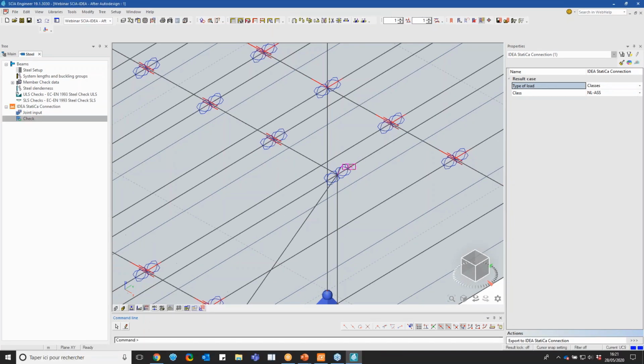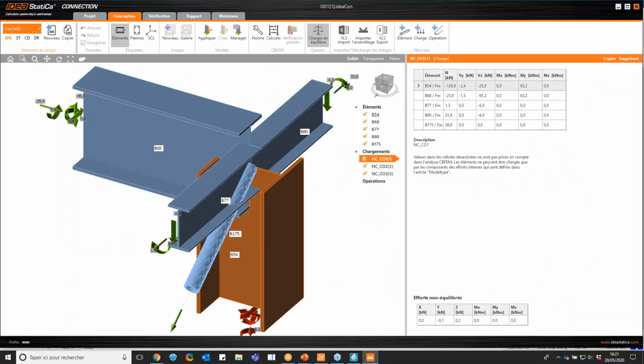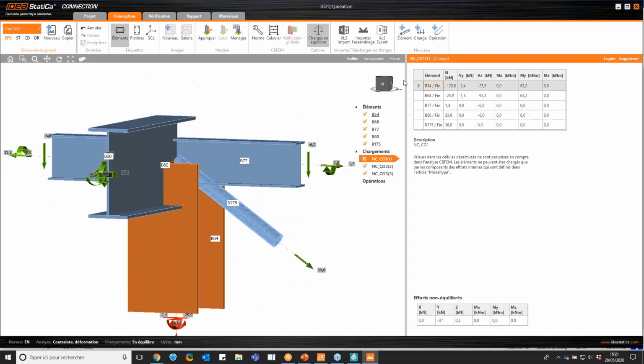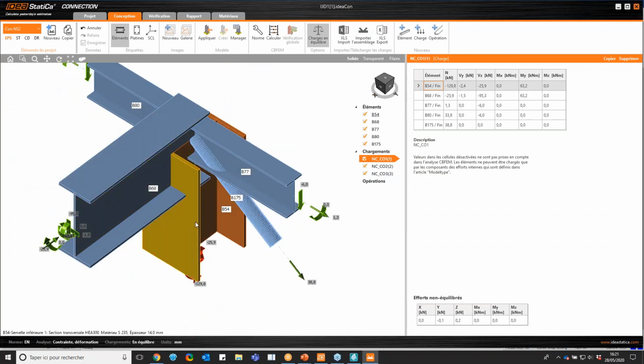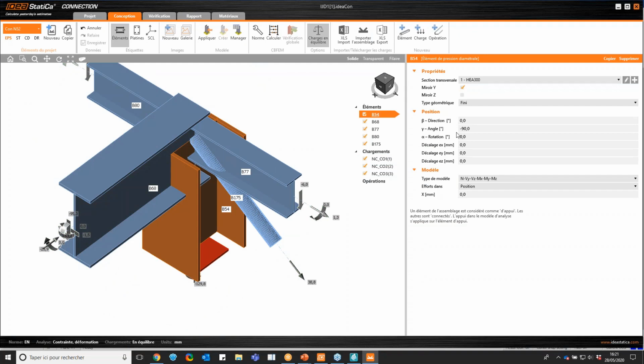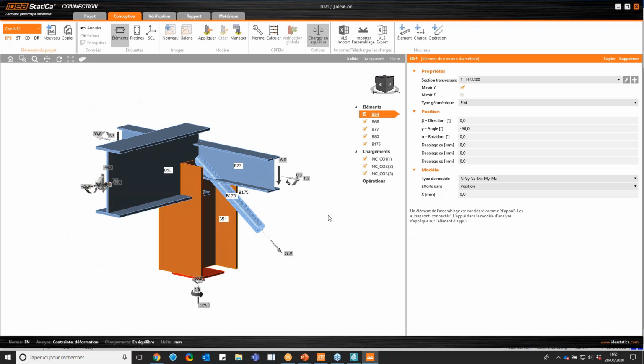What we will export is the analytical model of this element, so the node with those elements defined, and also it will recognize all the sections, and the direction and orientation of all the elements. So as you can see, all the orientation, if I have, for example, a certain angle in my elements, it will be recognized, and all the efforts are exported.